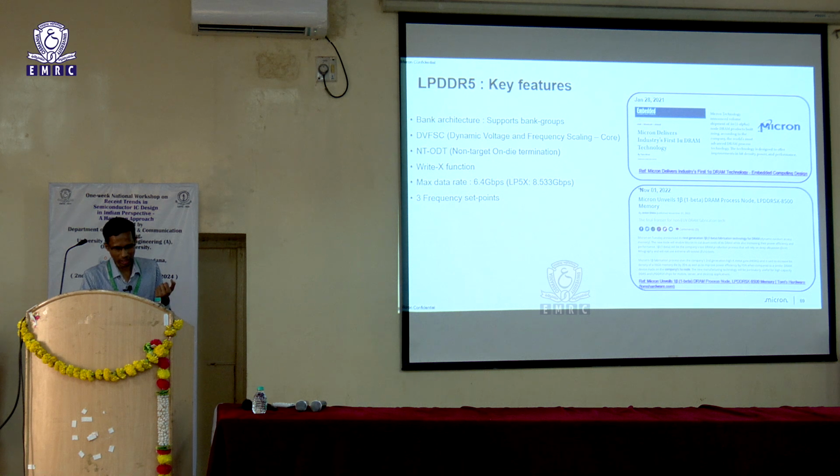Next is NT-ODT, non-target on-die termination. I will talk about it using a slide. Then the Write X function, I have a slide for that as well, and speeds have increased. The LPDDR4 catered up to 4.2 Gbps. This goes up to 6.4 Gbps, and then we have LP5X, which is 8.5 Gbps. And the earlier one supported 2 frequency set points, this supports 3 frequency set points.